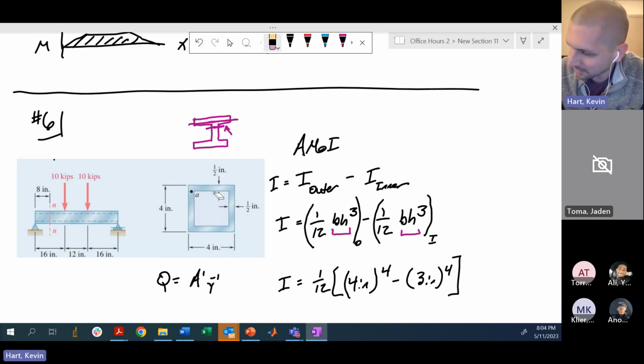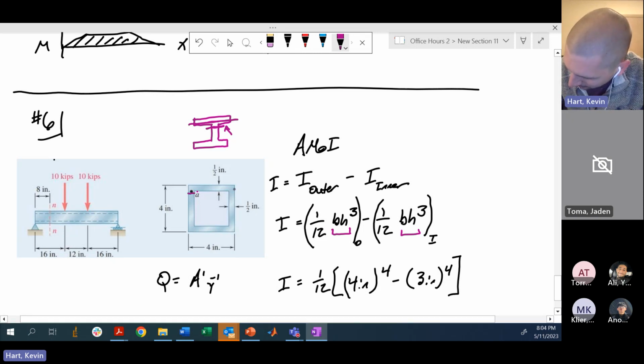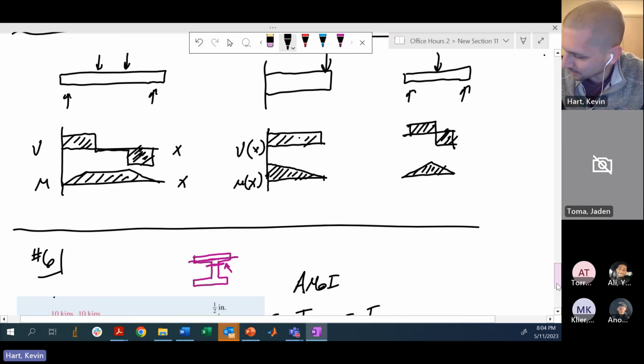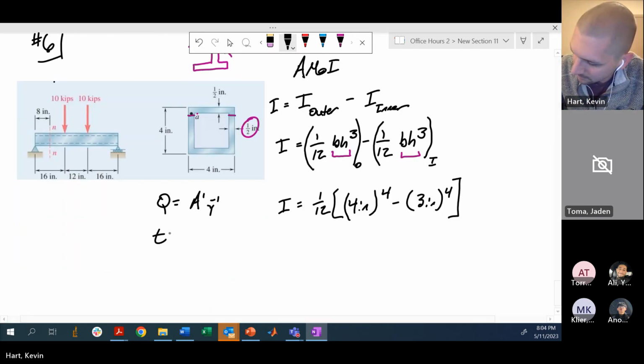But you've got to be careful, because the full width of the piece at A is not just this little slice. You've got to go across the full width of the beam, which is 2 half-inch segments. So the total thickness for this portion of the box beam is 2 times 1/2 inch, which is 1 inch.